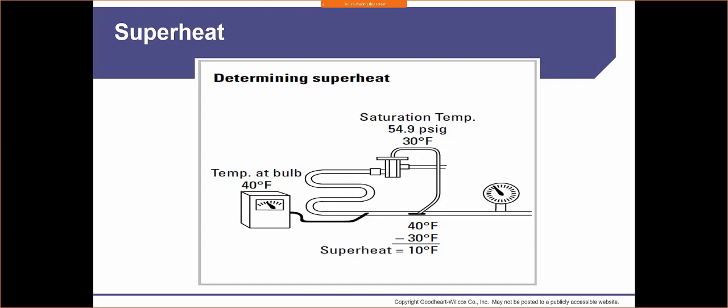With the little asterisks thrown in there, scroll compressors are a little bit better at being able to pump liquid refrigerant if it happens, but we still don't want it to happen. So we want to make sure that we have that superheat involved. That being said, this drawing is actually incorrect, and I just noticed it now.